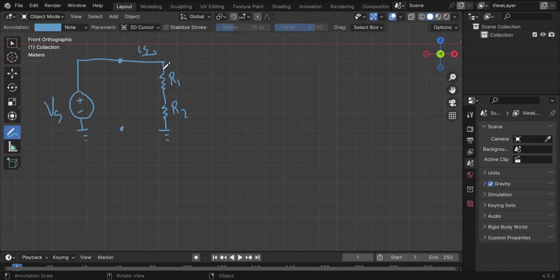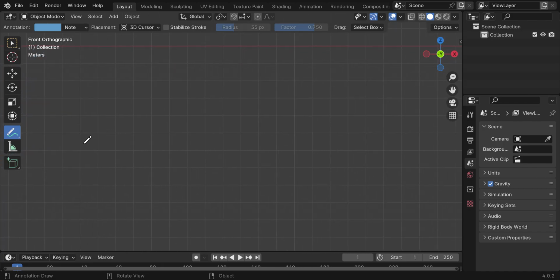Now this allows us to do some pretty interesting things, because what if instead of measuring across both, I just measure across one resistor? I'm not in this case going to see the same source. I'm going to probably see something less than the voltage source. But this voltage plus this voltage will equal the voltage source, because you're measuring off a section and then another section, but those 2 sections together add up to measuring across both of them, which we already discovered is the same as the voltage source. So let's go through one example of that.